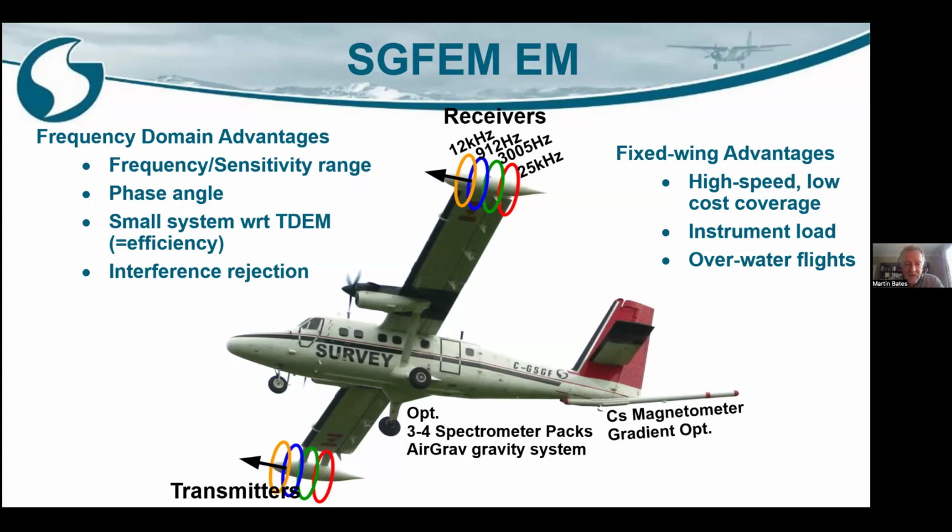And you see we have the four transmitters. These are coils. The system is set up so that different geometries of structures in the ground will be more sensitive to your signal, depending on the orientation of those coils. Anything which is coplanar to those coils, like a perpendicular and vertical structure in the direction of flight, if it's perpendicular to us, that's going to couple with the field the most and give the strongest response.